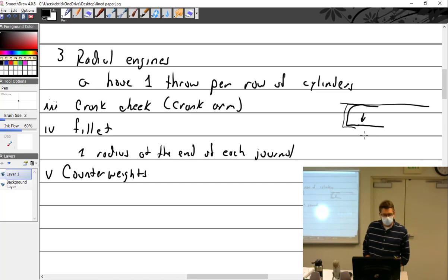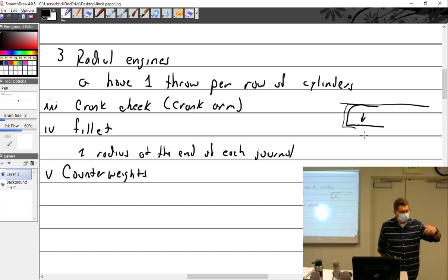So what are they and why are they loose? Well, those are dynamic counterweights, and they're designed to take out certain vibrations. And it's funny, because when you read, especially Continental, they use a lot more. Lycoming uses them, but Continental really does. Some of their 6 cylinders will have 3 sets of those things, and they just talk about it. Well, that's the 4th order and that's the 5th order. Then you have 2, 3 orders and then another 1st order. And you're like, okay, I'm supposed to know what this is. But they label them that way, by position and order.